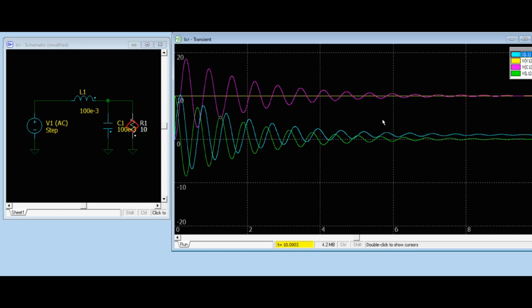Steady state continues. The circuit then settles into a steady state where the capacitor is charged to the source voltage, and there is no further current flow. Output voltage stability. The output voltage across the resistor remains constant once the capacitor is fully charged, and the circuit reaches a stable condition. Implications.